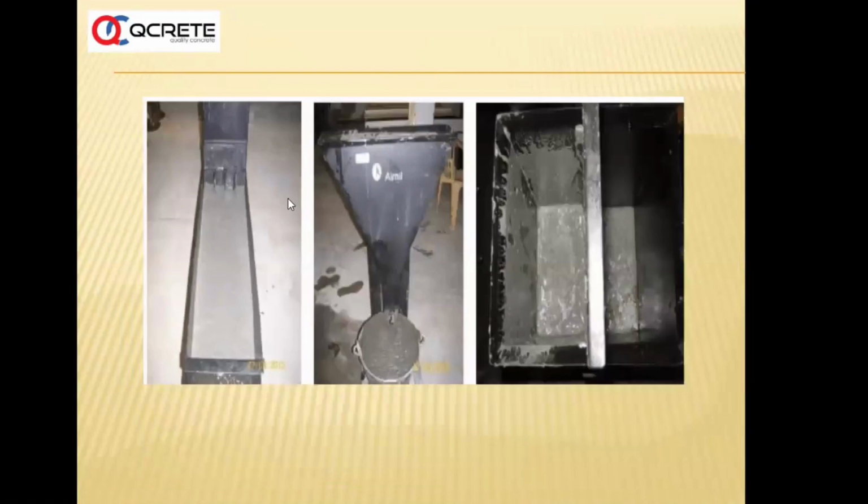There is a V funnel test also, where you fill up the concrete here and open the shutter here. This has to be collected within 8 to 12 seconds normally. If this takes more time, then this concrete is not a self-compacting concrete. So that is how these concretes are checked once it reaches the site or before using.